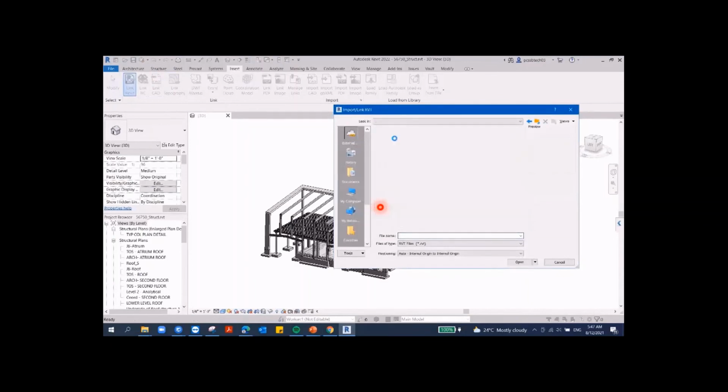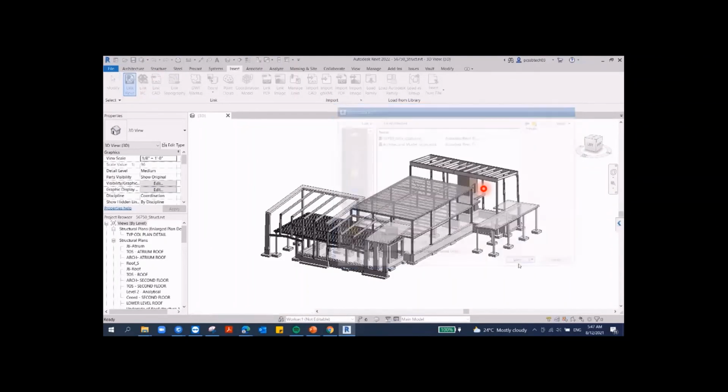There is an option for external resources where I can open BIM Collaborate Pro and search for the architectural model that I have consumed from BIM Collaborate Pro. I open up the consume folder. Only then can I access the architectural model, and then I can bring this model into my model.